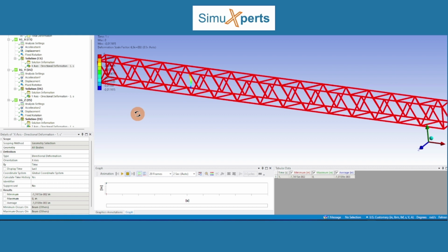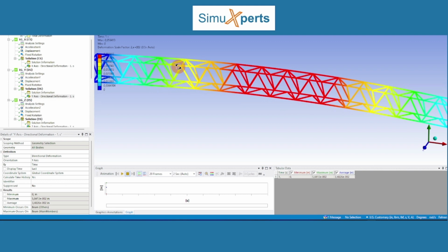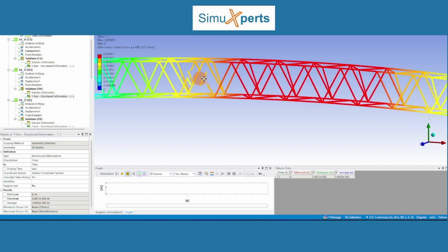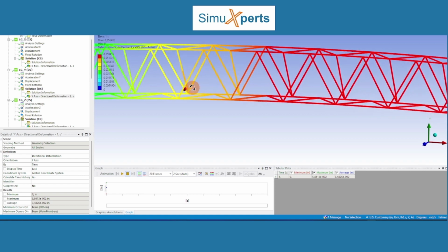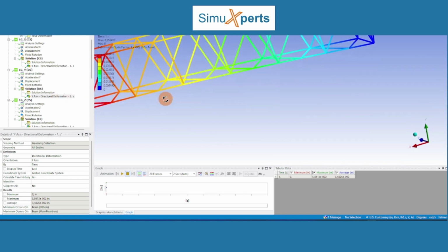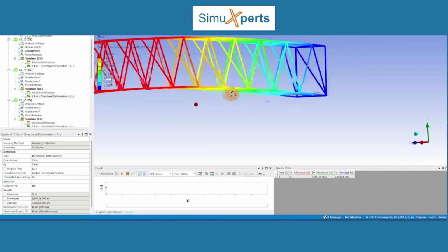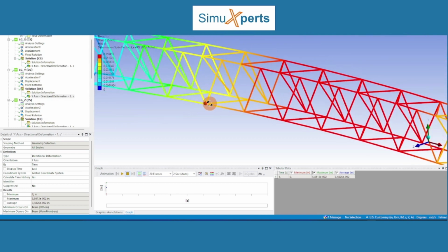X is really the best direction here. It depends on the problem. So that's why I always do a 1G in X, a 1G in Y. In this case, Y doesn't speak as clearly. You can tell that there's a discontinuity here. The diagonal is dark yellow at the bottom, whereas the back diagonals are yellow, clearer yellow. So there is a discontinuity at this joint. So it means that these members are not properly connected.